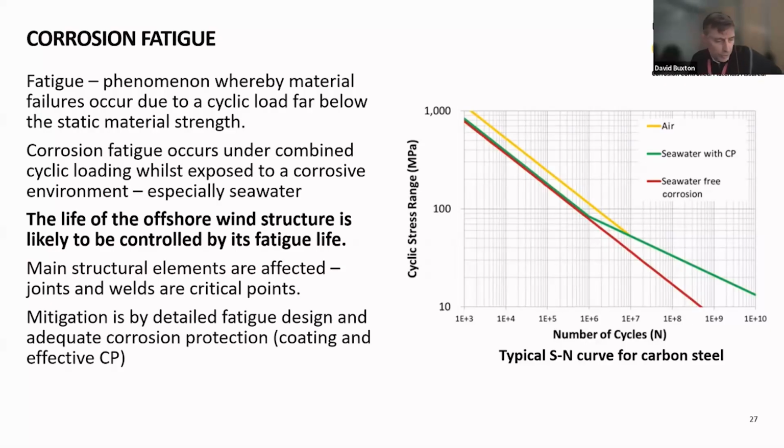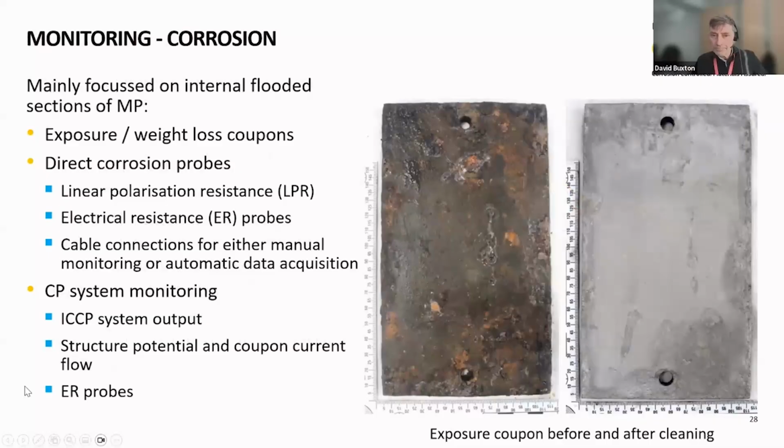And just to finish off very quickly, a couple of slides on monitoring. We've talked about the application of mitigation to minimize corrosion. So if I could have the next slide. Then we need to assess whether the mitigation options that have been applied are being successful. And there's several options for the monitoring. Perhaps the most commonly used is exposure of weight loss coupons, and I've put in a couple of images there of a retrieved sample, and then one after cleaning when the weight loss would be recorded.